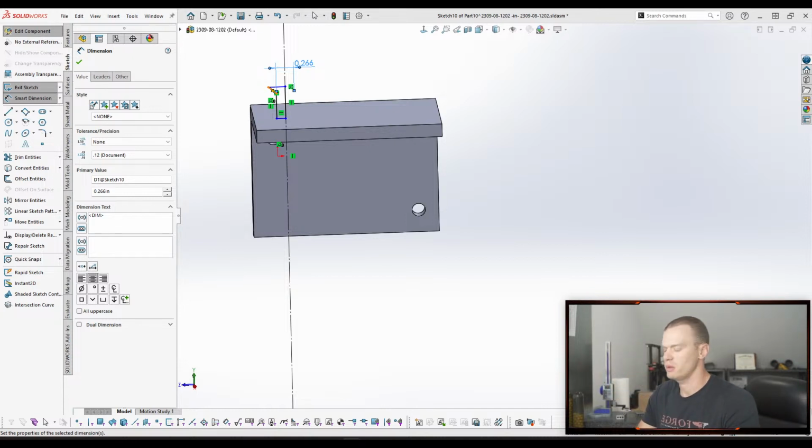Quarter 20. Wait. Not a 1/4-20. So based on the hole, it's a 1/4-20, but based on the screw that came in it, it's a size 10 screw. So it looks like they're just allowing a ton of play in their through holes. Okay. So they're just allowing a lot of extra play in their through holes for some reason, which is fine. And it's .285.